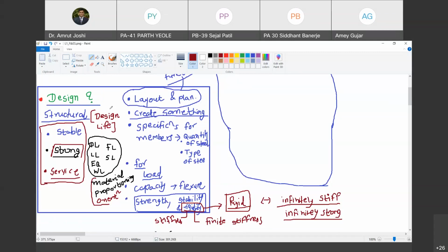Yes, sir. But if you take into account reusability of the formwork, you have to use that formwork for multiple sites. Then again, its design life and the load repetition cycles that it has to sustain become different. Do you agree with me? Yes, sir. So here we can take one more thing: when we design a structure we also may need to design it for fatigue. So what is fatigue? For example, you must have seen the train track sleepers. You have seen the sleepers connecting two rails, placed at a regular interval, right? Are you with me?